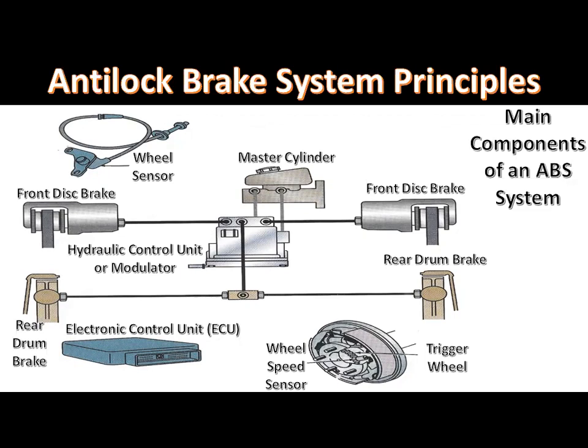If the tire slips about 15% without wheel lockup, cornering traction is greatly improved. Since the ABS provides about a 15% tire slip without wheel lockup, even during panic stops, steering control and vehicle stability are significantly improved. If a wheel or wheels lock up during a panic stop, the vehicle may swerve sideways and the driver may lose steering control.